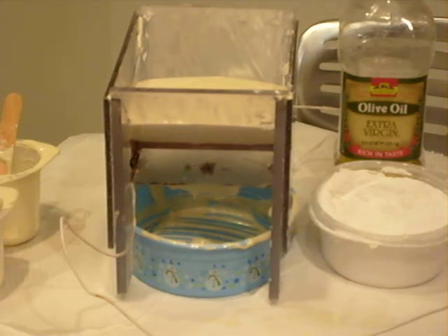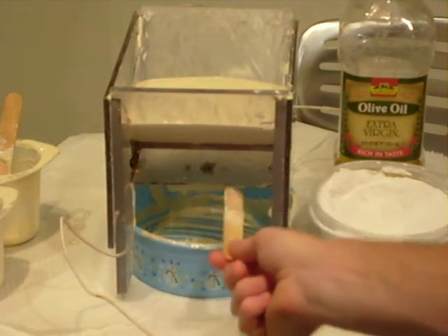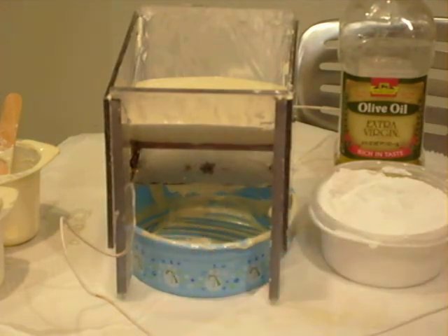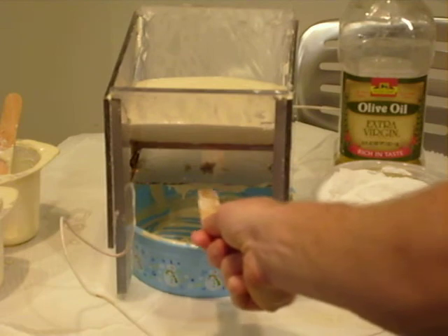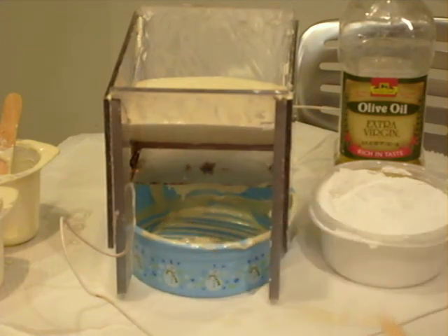We also had some trouble with short-circuiting the circuit, and we had to remove our fasteners and replace them with non-conducting glue. We tried to use nylon screws, but we found that the fluid would find its way into the thread of the screw and short across. Hence, we have the thin plastic layer to prevent the conduction through the fluid itself. You can notice a nice laminar flow. It's rather slow, but it does show nice flow characteristics.